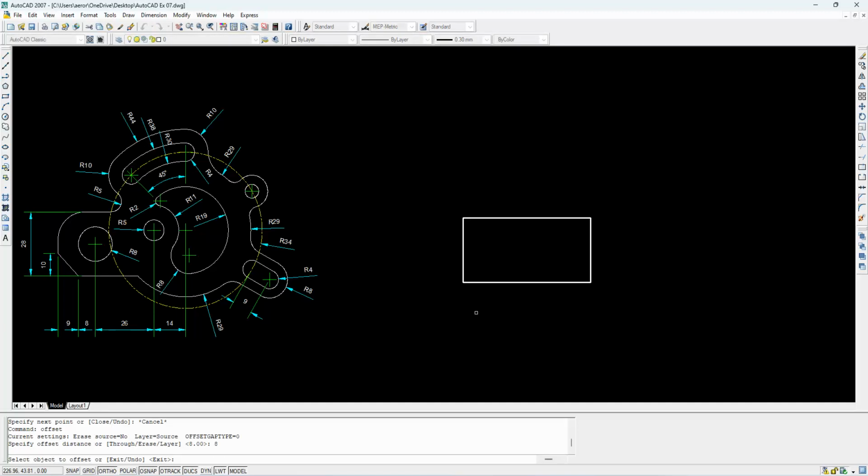Draw an 8 mm line from here to here. So control, circle, a smaller circle, control right click from here at 32.5 comma, y-axis it's 20. So from this point draw a radius of 4.5.